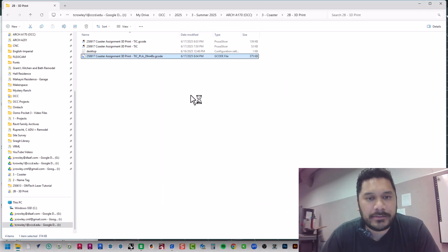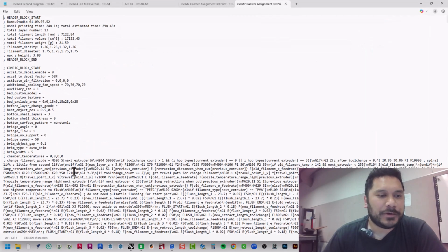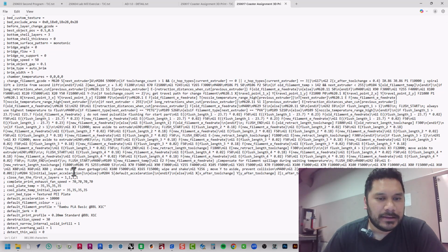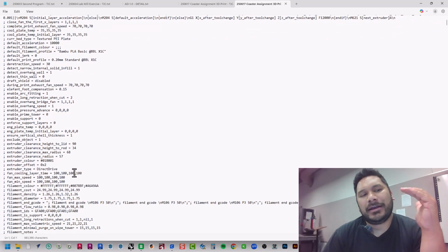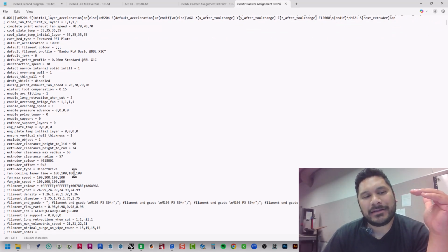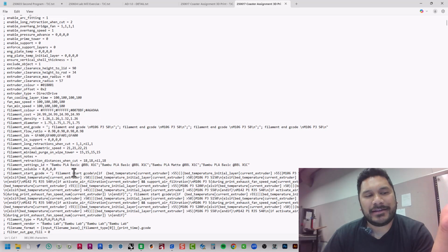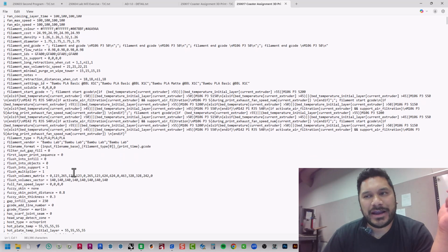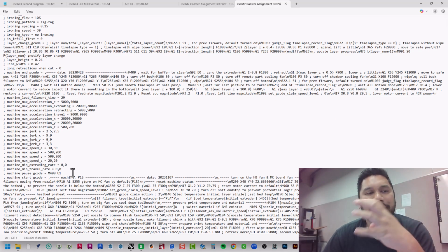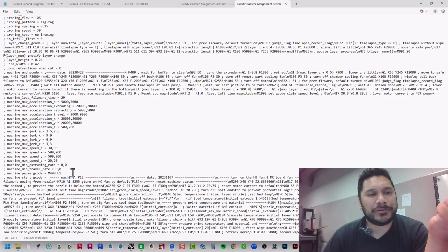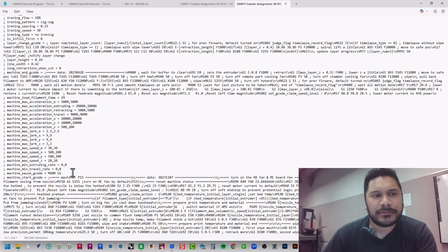There's a whole syntax of commands, a whole library of different commands that G-code is accessing during this procedure, and it's outputting this as basically a text file, and this text file is going into the 3D printer, and the 3D printer is reading it, right? Think of it as like robot language. So the slicer creates this language. It says, hey, grab the extruder, heat it up, move it from this point to that point, to this point, to that point. We're going to go up 13 layers to get this done.